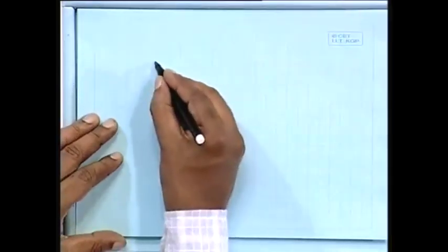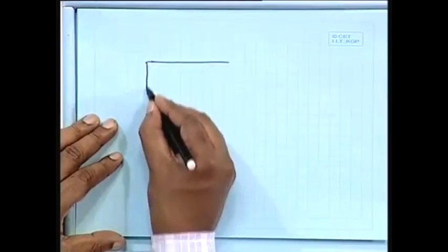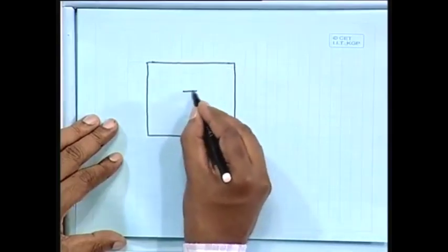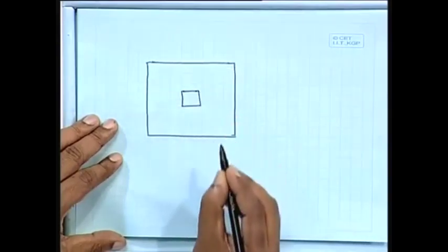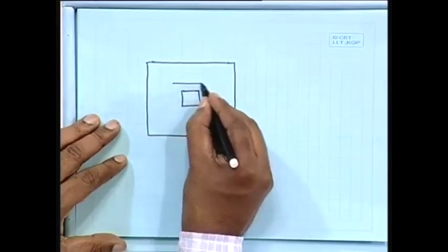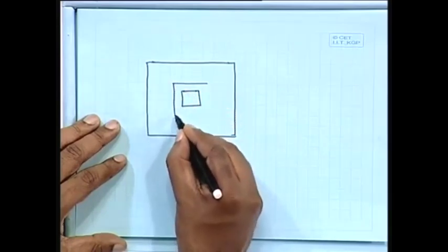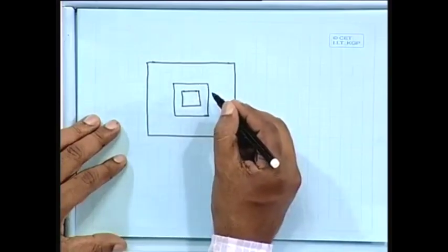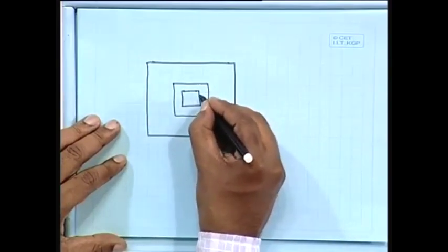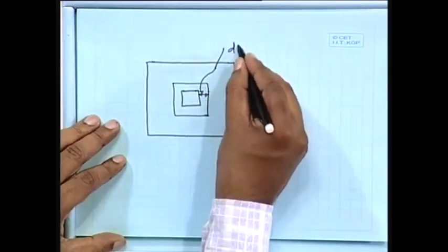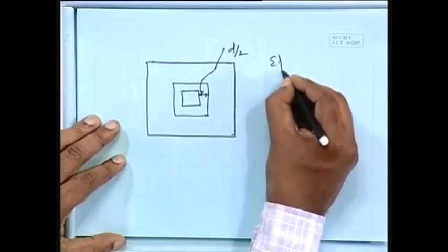And what about the punching shear, or two ways or both ways? It means that this is the column position. So, we shall go all along in all sides, and this one will give you a section at a distance D by 2. D is the effective depth of footing.